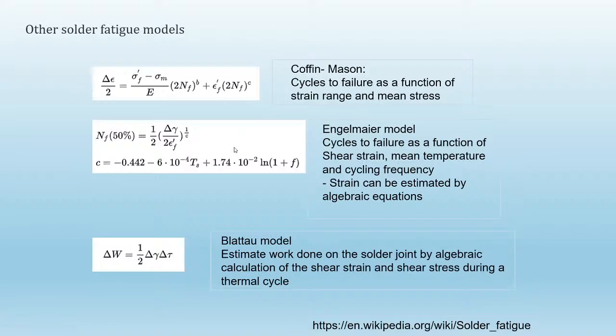Fatigue is always going to be something you match to experimental data, and that's what was done for these methods. I want to say that the Plateau model is available in Ansys Sherlock, and this is the method we use in Sherlock to do system board level thermal reliability.